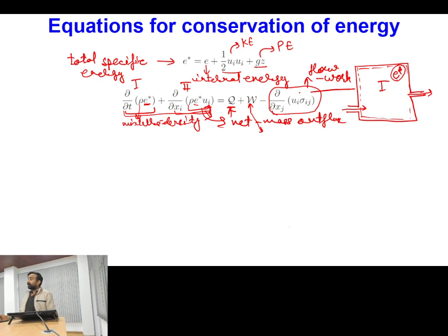Along with the flow work, there is one more term in the energy equation, which is called the viscous dissipation term. If your stream is moving, then that stream is pushed by some pressure at a certain location. The amount of energy we invest to make that flow happen, we account for with the help of pressure into specific volume into mass flow rate.